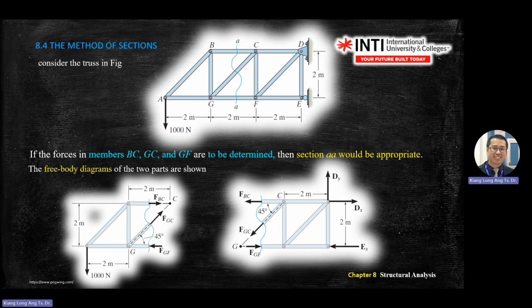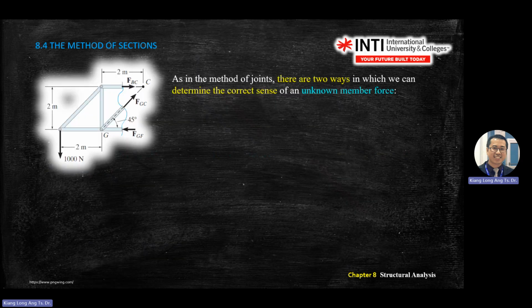Okay, just want to highlight, remember to copy the reference point. For example, the member BC, there's a C point there. Remember to copy the line there, because you need the length to calculate for BC and GC. You need the point for the calculation.